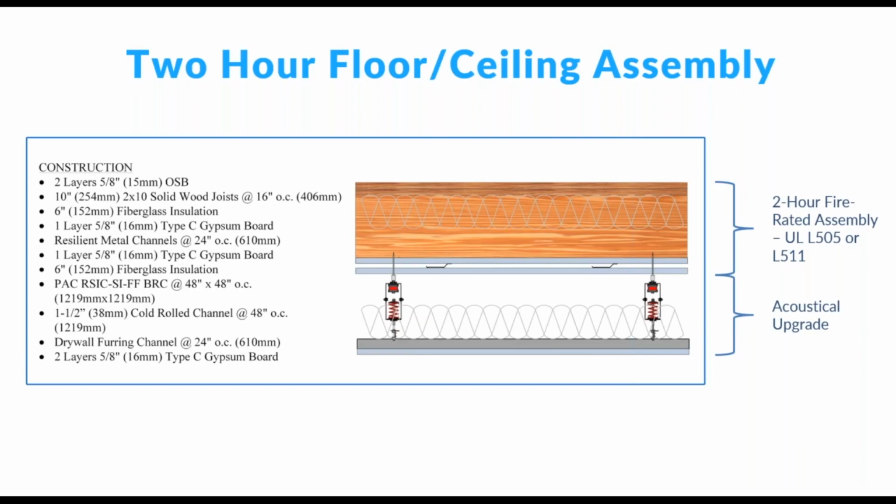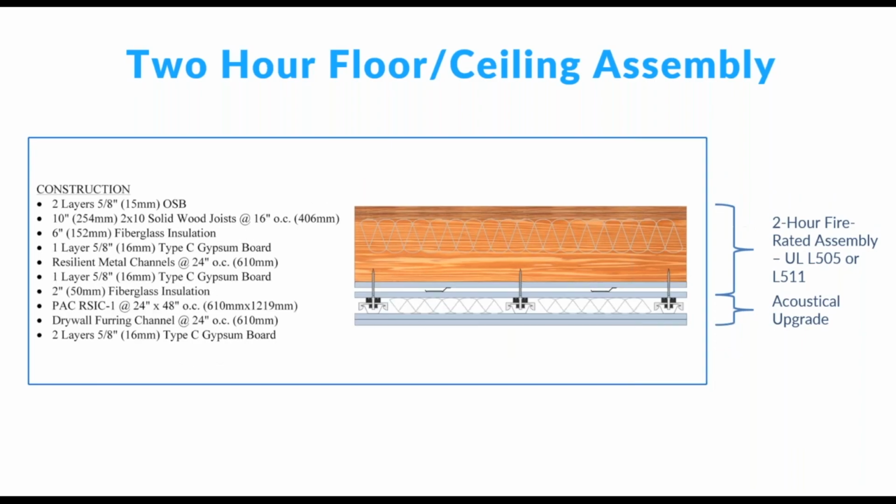It works really well, but spring isolators can be expensive. They also take up a fair bit of space. You might not always have the space to drop your ceiling that much. So another option is to just use sound isolation clips and attach them directly. It takes up a lot less space, but it also doesn't work as well acoustically because you still have this fairly small air cavity. This one's bigger and it's got some insulation. We can fit some insulation in it, but it's still not as great, but it might get you there depending on what your target is, right? And what your noise source is and that thing.